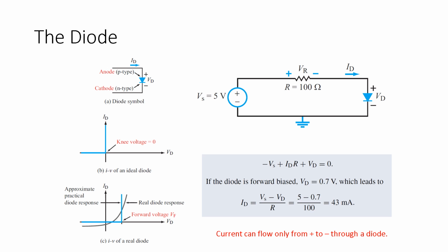And so diodes have two parts. They look like resistors usually, except they have a single band on them, and I'll show you some pictures of it. But essentially, they have an anode and a cathode. And the anode allows your positive voltage to come into that side. The cathode faces the negative voltage or your ground supply. And as long as it's in that direction, current can flow through it.